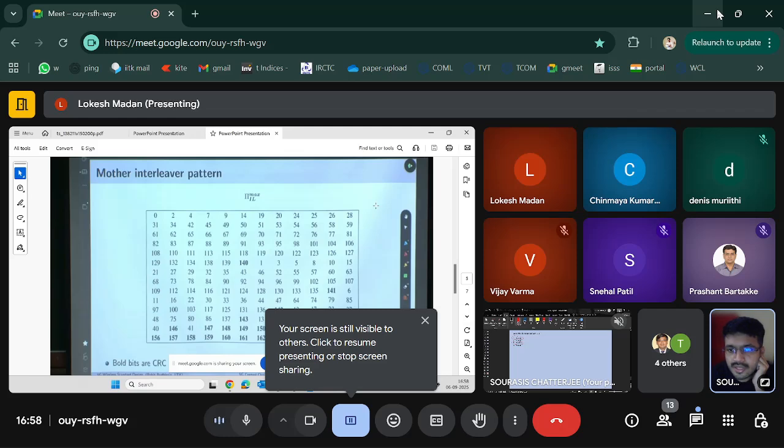How to read that thing, right? Yes. So these numbers you are seeing, you first of all need to read them in a row-wise manner. You complete the first row and then the second row and third row, and the numbers basically denote the position of the bits in the original sequence. So for example, if you pick the elements of the first row, that is 9. That means whatever input sequence goes, the fifth bit in the original sequence should go to the ninth position.